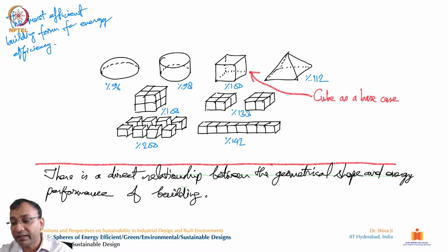The moment we take out those cubes separately, for example if we divide this building into two different floors, then it increases by 33%. It reaches 133%, and the exposure increases to almost double. In case we keep these 8 smaller cubes, which came from this block, in different places, see how the requirement of energy just got double. And in this one, if we keep them in a linear fashion, it is 142%.